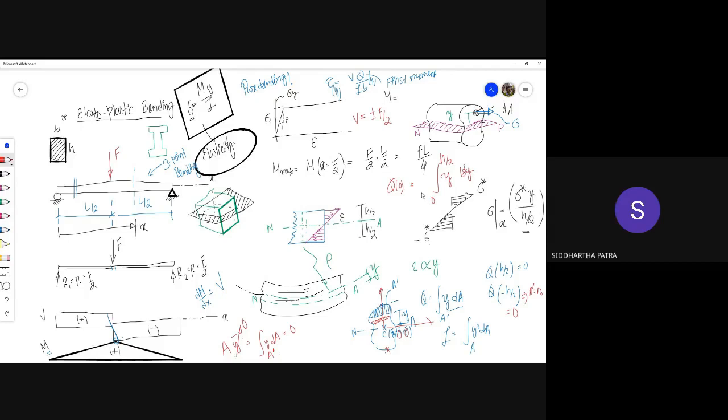And that is multiplied by V, but then you are dividing by I times b. So the two b's cancel out. So you only need to do integration y dy divided by I. I, by the way, is the second moment, and I believe this is the expression.